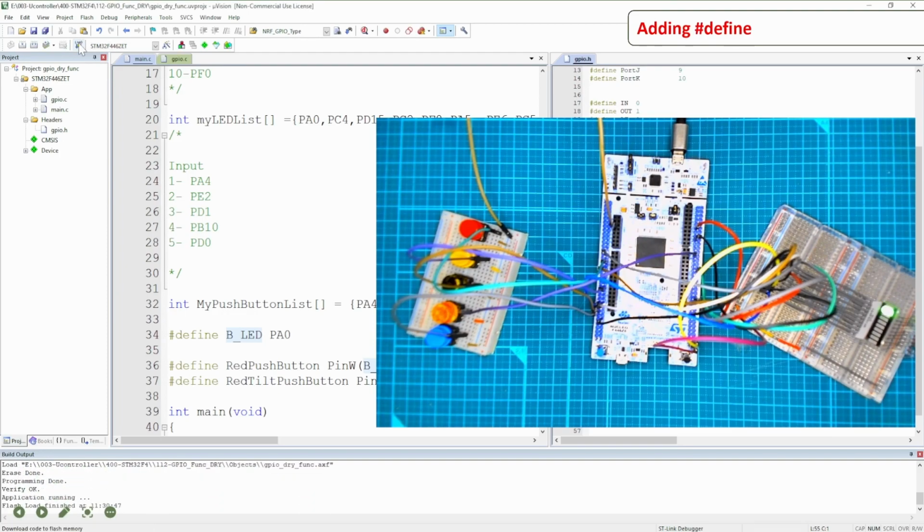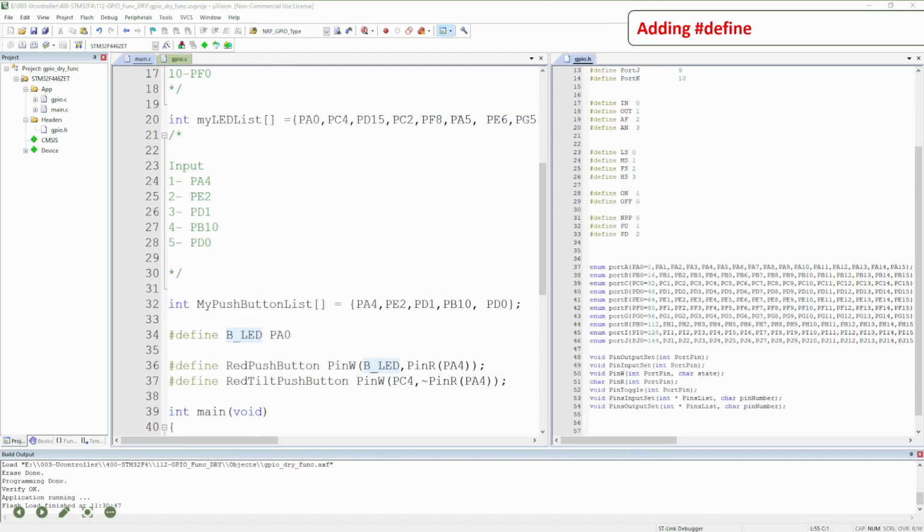Yeah, and I do have a green LED, which is the PC4 connected. So if I click here, it's switching to the blue one, which is exactly what we wanted. So you can use this define to optimize further your code. For example, you can also define, and this can be used locally in your main code or when you have an application.